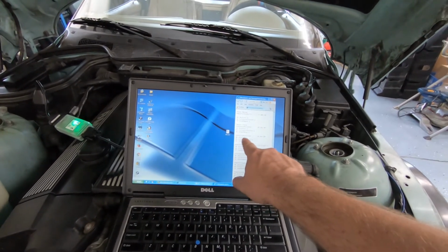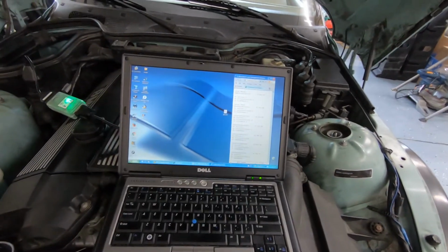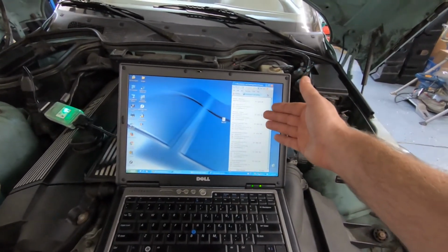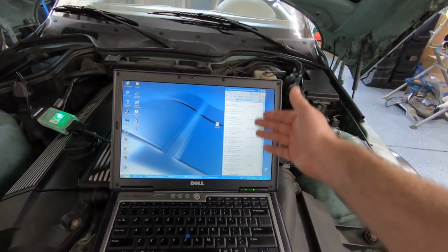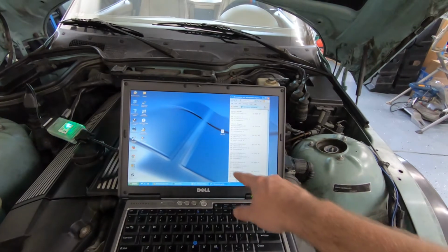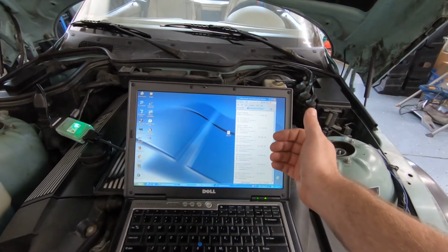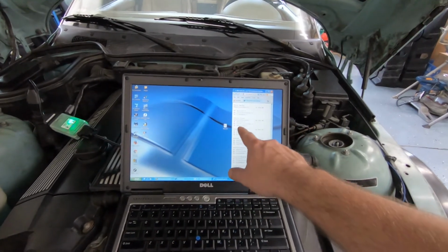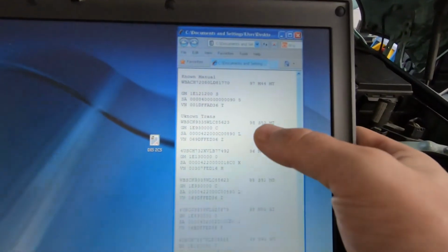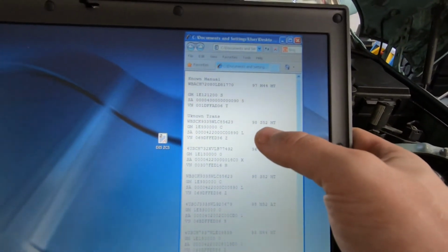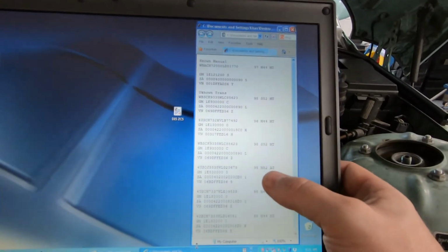They also have the VIN number for that vehicle on that label, so I typed that VIN into a VIN decoder and identified the year, engine type, and transmission type for that VIN, and that helped me narrow down which ones had a manual with the 6-cylinder engine. And from there I found that all the ones I found with manual and 6-cylinder were the S52s, so the M Roadsters or M Coupes.